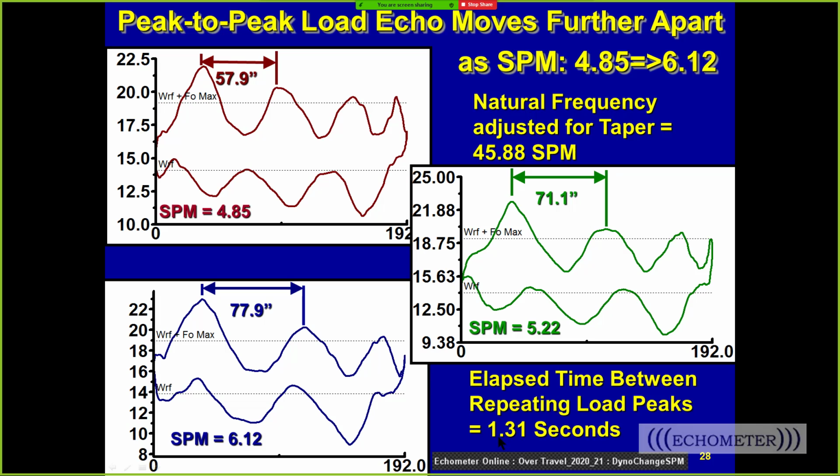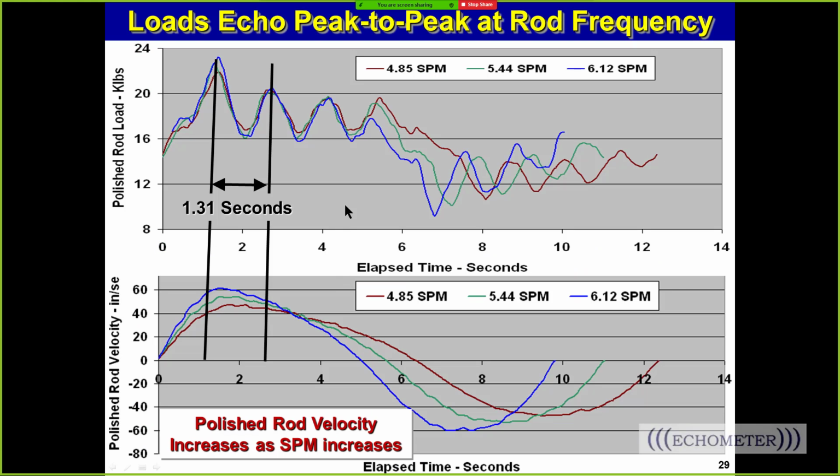And so it takes 1.31 seconds in this well for the force, the peak load or the minimum load, to travel up and down the rod string, and that's a repeat echo in the rods. Now, what that means is if I take this load versus time, and I plot the load versus time on the upstroke, and I overlay it, the peaks match up.